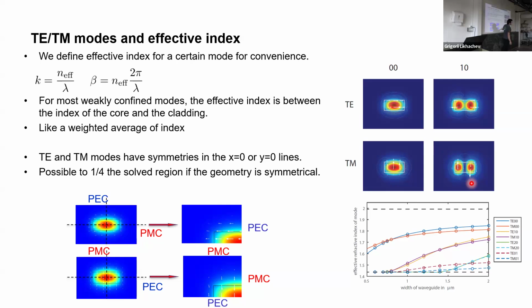After this: why don't you have a vertical component for TE mode? I thought TE means there is no electric field in the direction of propagation. That's true, I think that's for metallic waveguides. If you call it TE there, they have no electric field along the propagation direction.